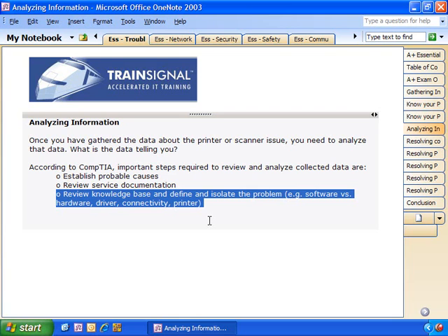And it was just the form. The forms were kind of at an arch, and if you laid the forms on a flat table, you would see a little bend right there at the end of the form, and that was what was causing the jam. So the paper was intact. It wasn't frayed. It wasn't cut in half or torn or anything. It just had a little arch near the end of it that caused the printer to jam. Nothing wrong with the printer at all. So you have to really try to isolate these problems and examine everything that's going on. Printers are very complex mechanical devices.